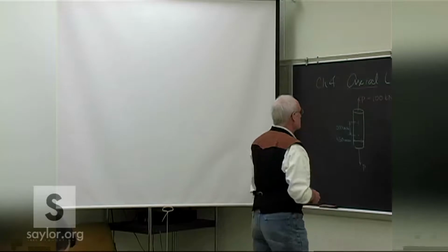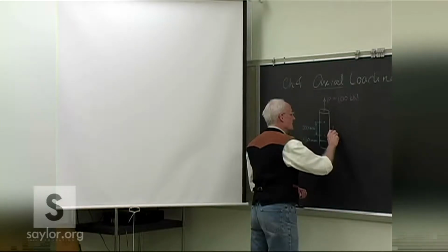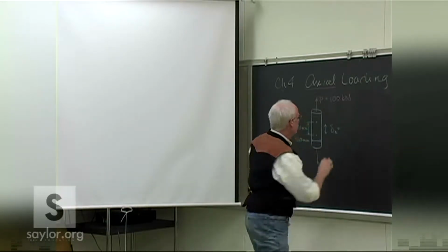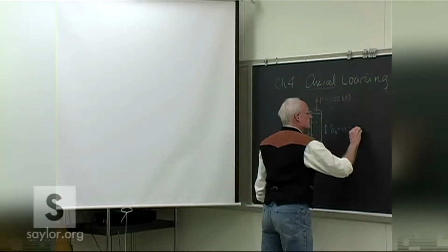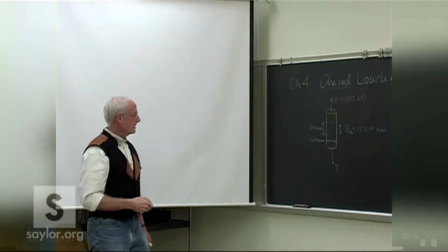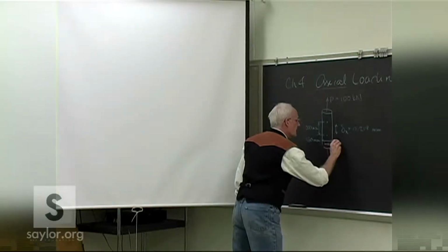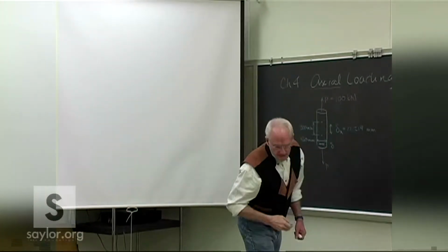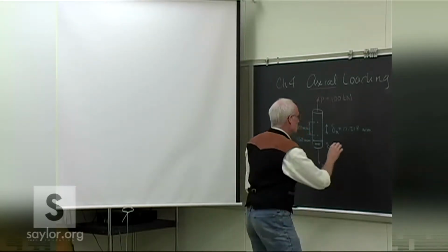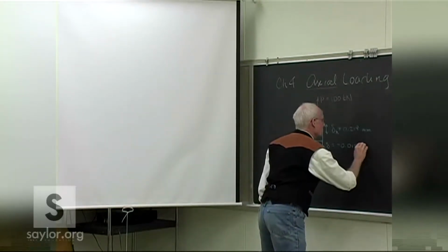All right, so we stress this part and we find that we get some kind of extension in the axial direction. Perhaps the test results are something like 0.2 plus a little bit millimeters, and actually it'd be a contraction in the radial, transverse direction, minus 0.01215 millimeters.